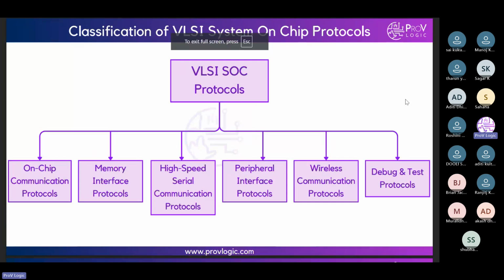So USB, just now you told, right? How we communicate from this one device to an external device. USB will be used there. And also PCIe. PCIe is internal to the system on chip only, to communicate high speed to high speed. Mostly it's also serial communication. Like that we have SATA, serial ATA, and non-volatile memory express will be there. Thunderbolt will be there. These are various types, which industries use particularly.